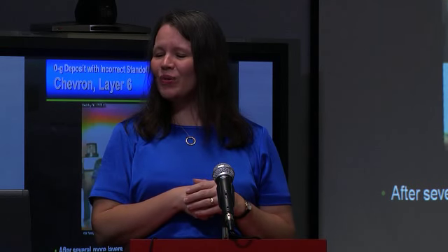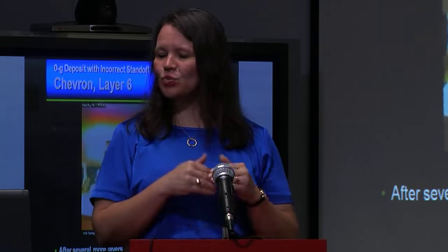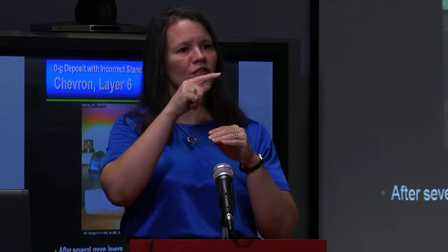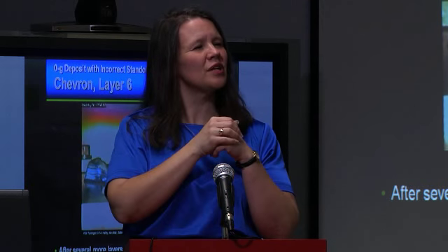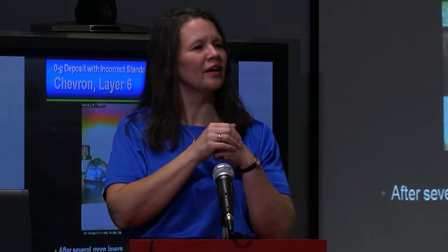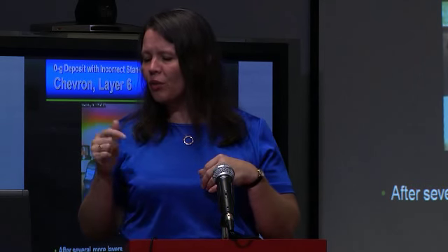So this is a couple layers later. So that was the first and second parabolas. This is layer 6. We didn't bother trying to fix it because we were going, wow, this is really cool. But what you see is as we get the height off, you can see as we come over the humps, watch the wire, and the wire is deflecting. This is 40 thousandths of an inch diameter wire. And so it's a fairly flexible piece of aluminum wire that we're feeding.